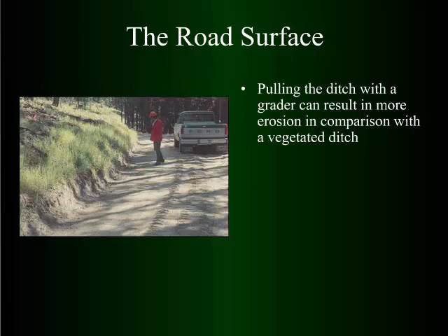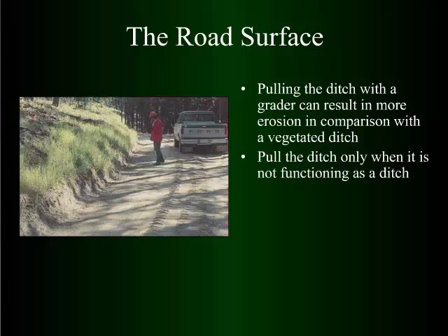The other thing is, when do you want to clean your ditch? If you've got grass in it, but it's passing water adequately, the grass will trap some of the sediment and help keep the erosion down. So sometimes you just have to look at how it's functioning. If it's got grass in it and it's functioning, many times it's best to go ahead and leave it alone.